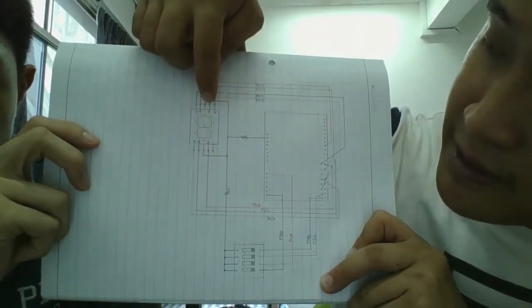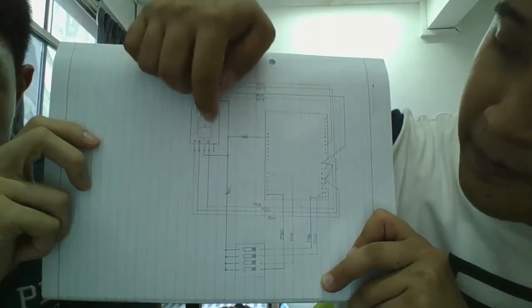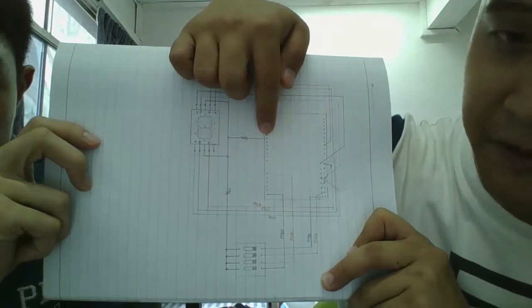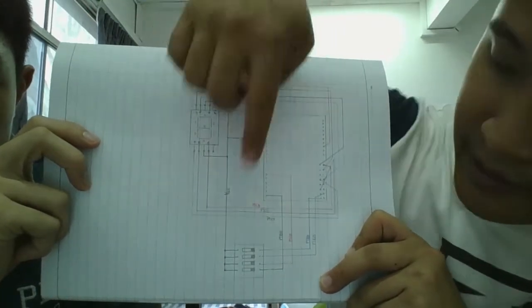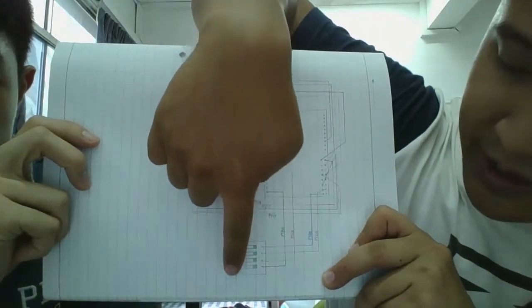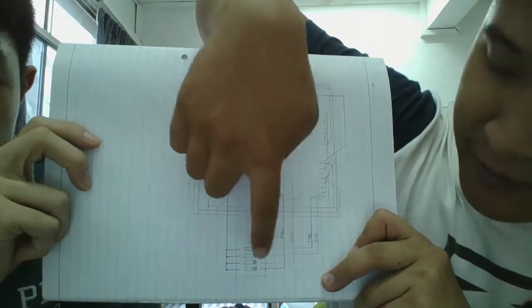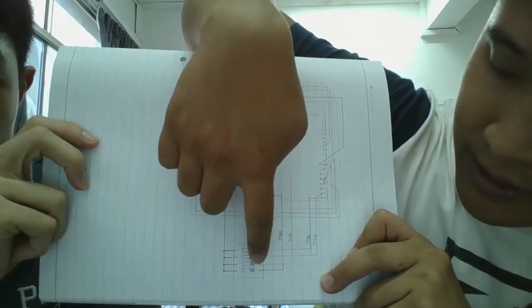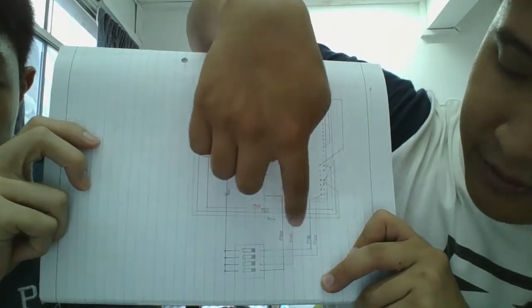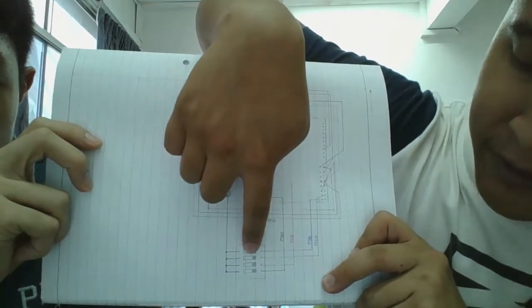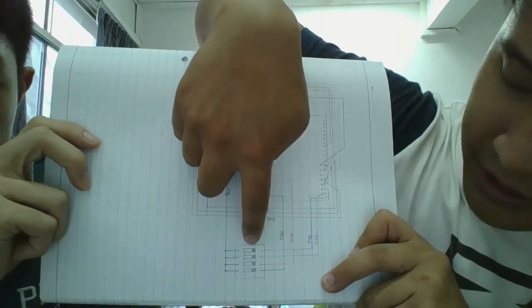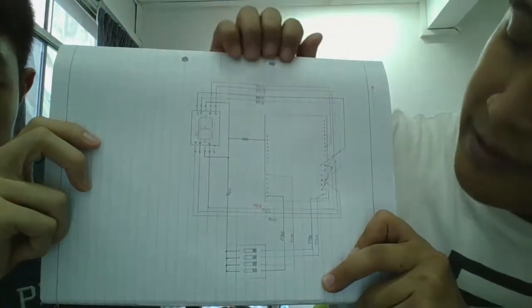Both the middle pins of the top and bottom of the 7-segment display are connected to the VCC 3.3 volts from the Freedom board, and one end of each switch is connected to VCC to provide the supply. Then for the other end of the switches, from the bottom up, the first switch is connected to PTB0, the second is connected to PTC0, the third is PTE0, and finally the top one is connected to PTD0.